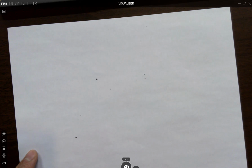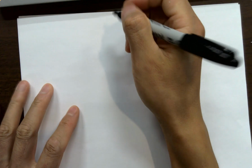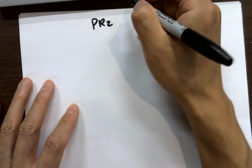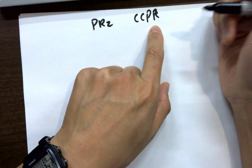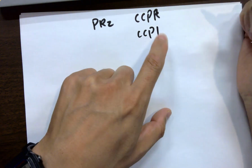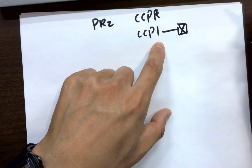So long story short, the PWM mode has two important registers. One is called PR2, for example, or PRx. Another one is called CCPR. Remember, CCPR is not CCP. CCPR is a CCP register. CCP is a pin. That's a physical pin, an output. It's a pin. Okay.